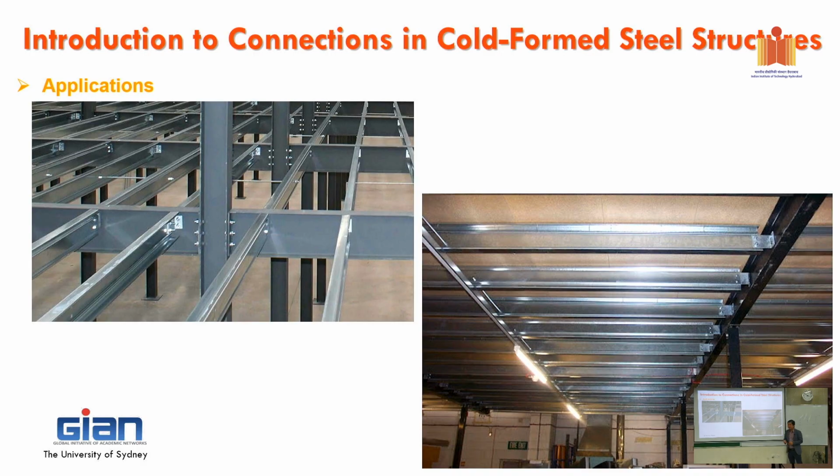Right, so very interesting, the problem with us as engineers, you have to calculate that. The reason I ask is that we have done a good number of connection tests. And we find that if there is more eccentricity, then the clip angle thickness needs to be increased. Oh, yeah. And if it is very close, then the clip angle is more towards shear. Yep. If it is a little farther away, then it increases twisting and the clip angle undergoes shear buckling. Yes, a lot of problems, right?